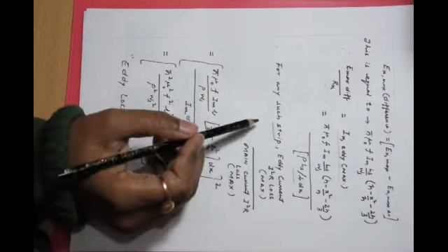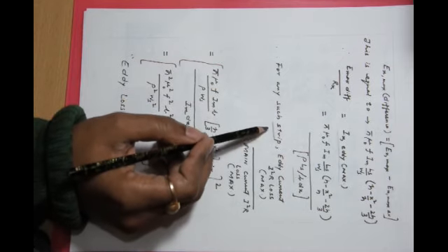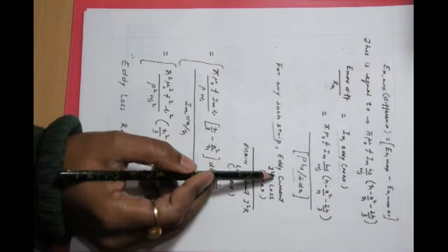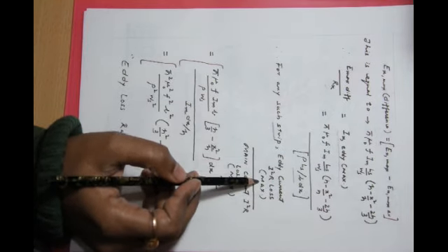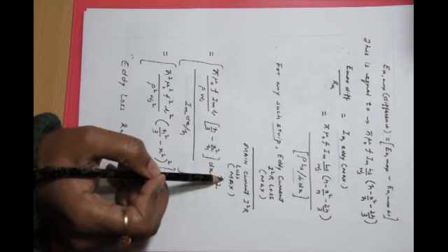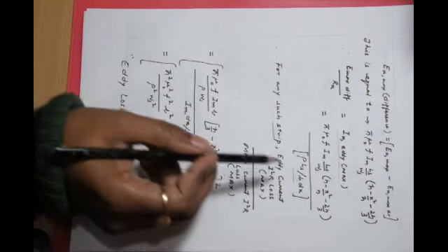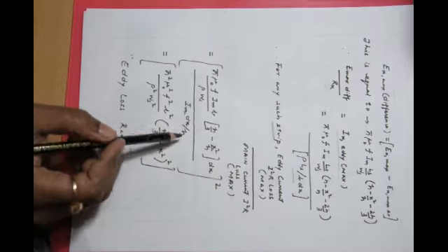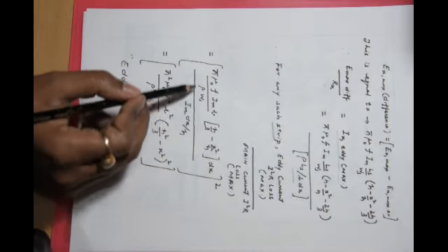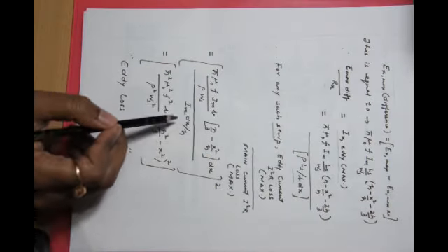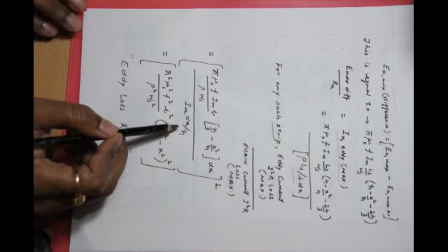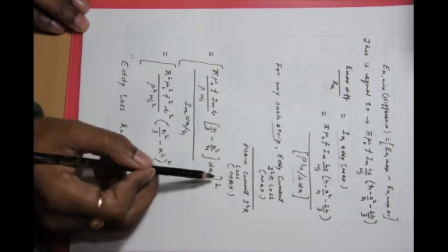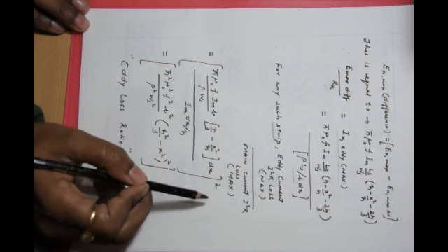Now what you calculate is eddy loss ratio. Eddy loss ratio is given by eddy current I square loss max by main current I square loss max. We have calculated the eddy current in the element is this much. This on simplifying becomes equal to this much. This divided by the main current in the element square into resistance.